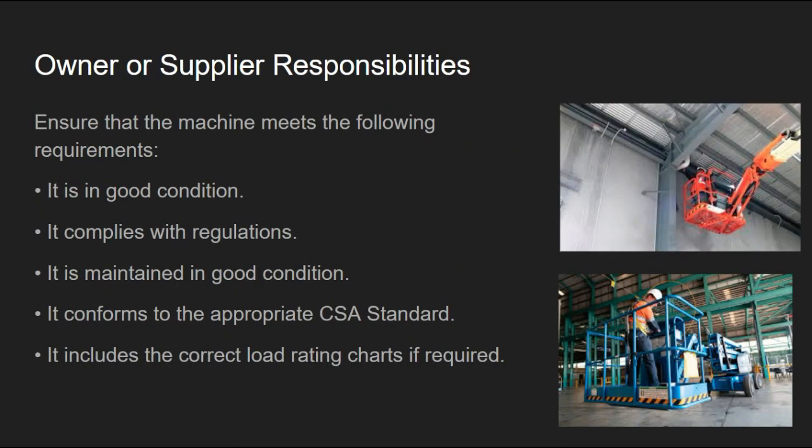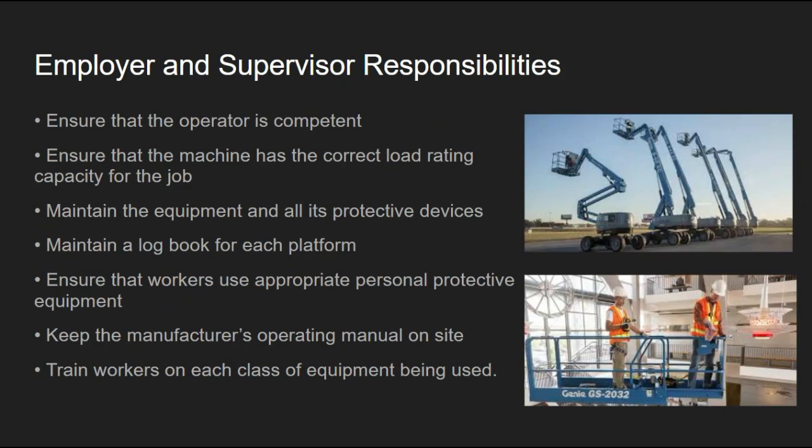The owner or the supplier responsibilities. So bringing out a lift to the site, whether it's an owner or from an equipment manufacturer, they've got to make sure that it is in good condition, it complies with the regulation, it's maintained in good condition, it conforms to the appropriate standards, and it includes the correct load rating charts if required. So the lift's now on site.